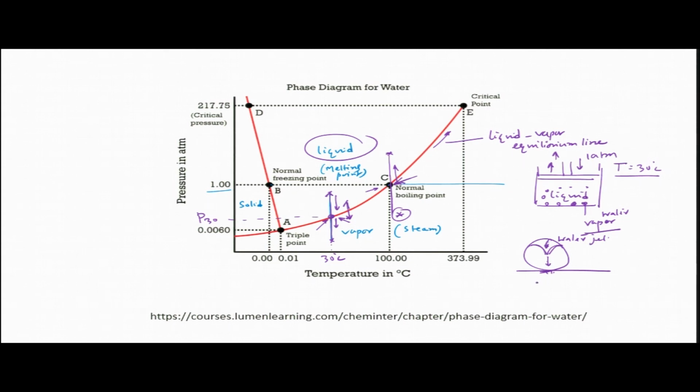So, that pressure could reach up to around 500 MPa. So, you can think of the kind of pressure it exerts on the metal surface because of this collapse of a bubble, and that bubble contains nothing but steam or water vapor. So, now if that happens, let us say this surface is a soft metal, let us say mild steel. The mild steel strength would be around 200 to 250 MPa yield point.